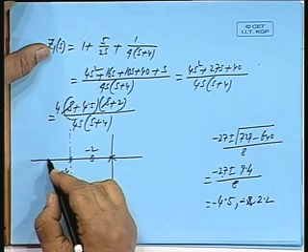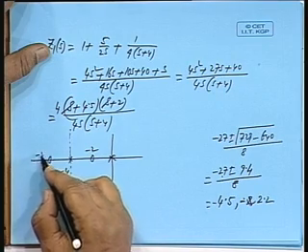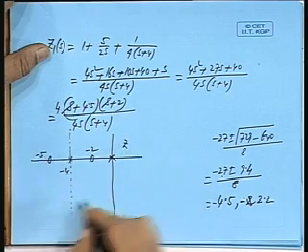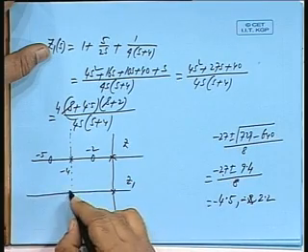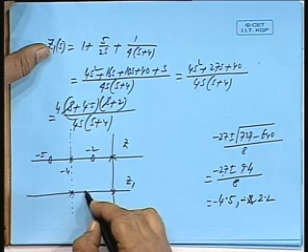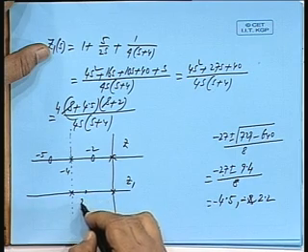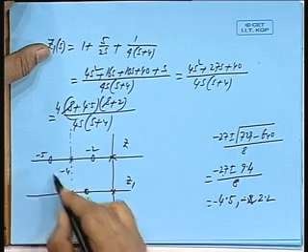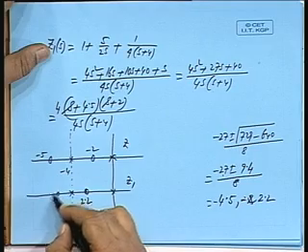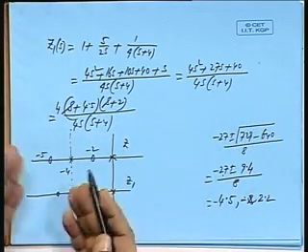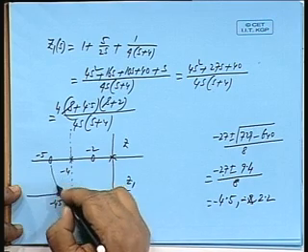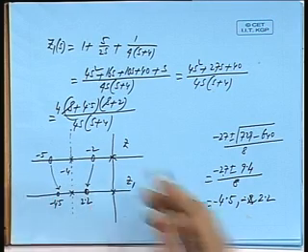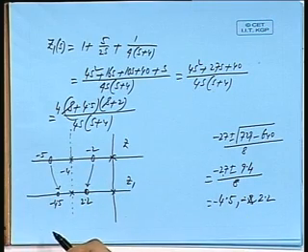Then it was at 5. This was Z, and Z1, this is a pole, this is a pole. So 2 becomes 2.2 and this 5 becomes 4.5. You see, now both of them are coming towards this pole. So the shifts are in opposite directions, but they are towards the pole. This is what I wanted to stress.